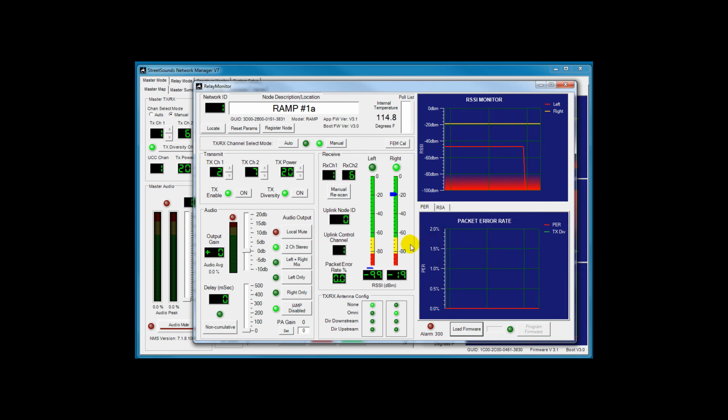So we send everything out in packetized digital format. We send it twice. We send it once on antenna 1 on transmit channel 2, and we send it a second time on antenna 2 on transmit channel 7. That's assuming you have 2 antennas. If you don't have 2 antennas, both of these packets get sent out on the one that's enabled. So in this case, the omnidirectional antenna is getting both transmit channels 2 and 7, burst number 1 and burst number 2.